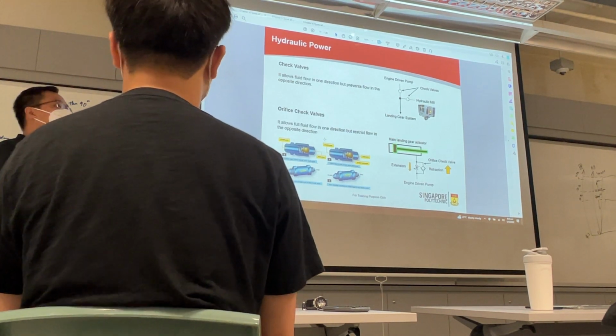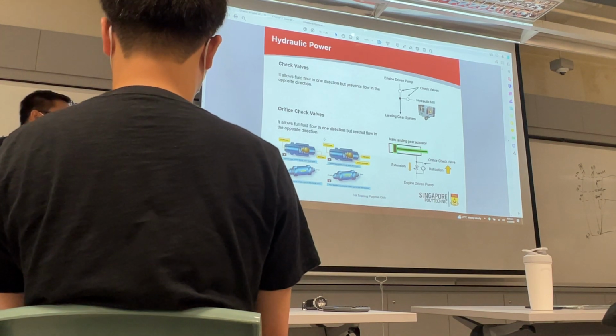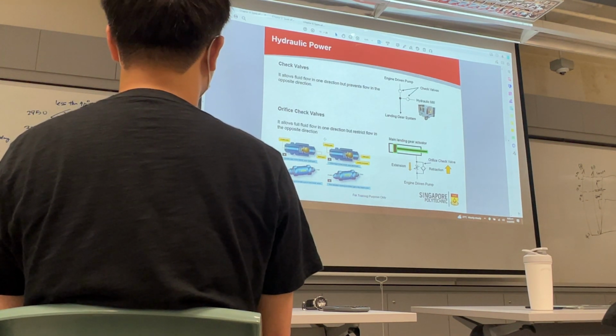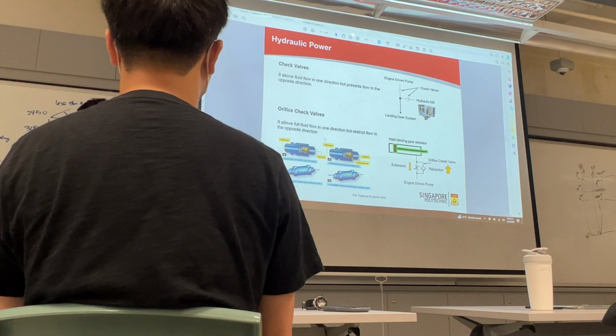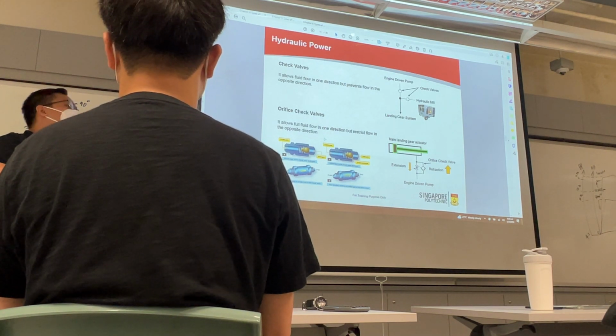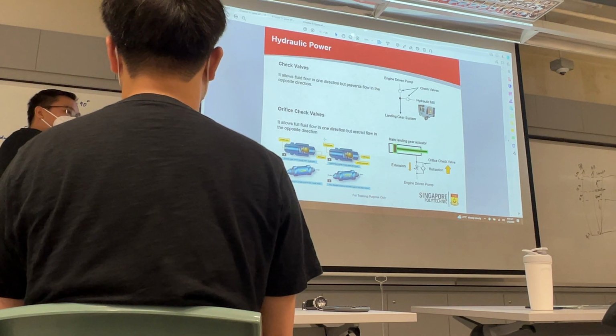When we are extending, it's different. The door will open first. The door open already, then the landing gear will drop by gravity. So it's assisted by your hydraulic fluid as well. Now, if you allow 100 to go as well, the landing gear will extend with a very loud bang at the end. Boom! Then what happens to the structure?